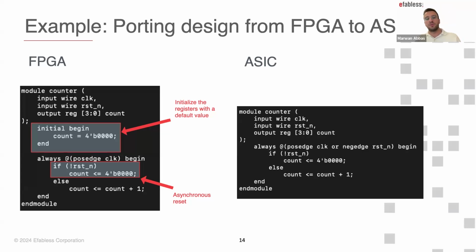But actually that wouldn't work in ASIC, because in ASIC we do not have an initial block, and if you even put an initial block, the tools aren't gonna synthesize it.